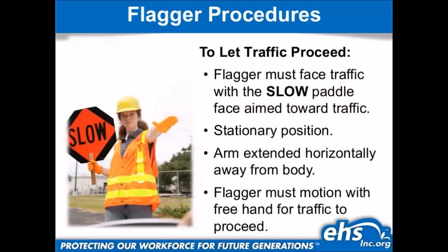Proceed, slow sign, and you're guiding them, waving them by. How you're delivering these signs matters as well. If you're doing it at a quick pace, and let's say you held them up for 5 minutes, and you're waving them by really fast, they're going to assume that you're telling them to floor it through the site. So again, calm, slow hand signals. Don't let your hand signals be misunderstood.